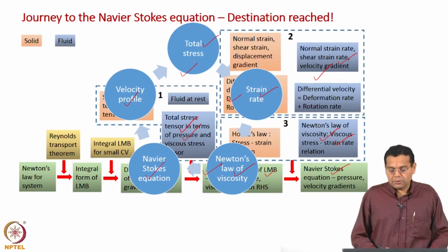Okay. Now, once we have derived the velocity profile, we can evaluate all the variables which we have introduced. Okay. For example, dou v x by dou y was a derivative. Now, we can evaluate dou v x by dou y, okay. And then physically meaningful variables like the strain rate, and then the viscous stress tensor, and then you can also show the stress element, etc. Okay. So, this helps us to understand the path we have followed and why we followed that.